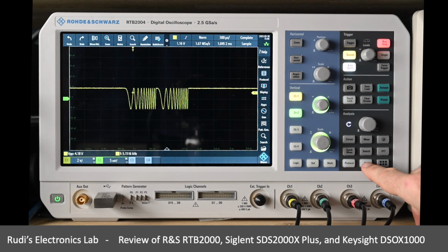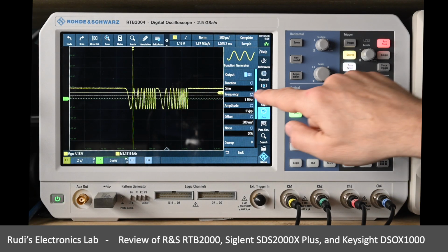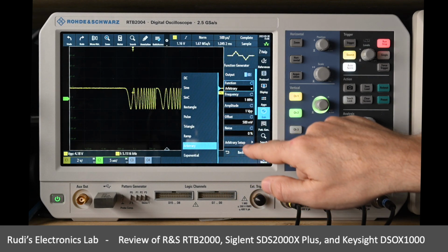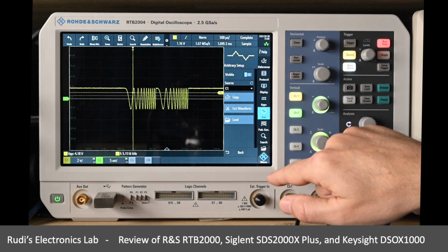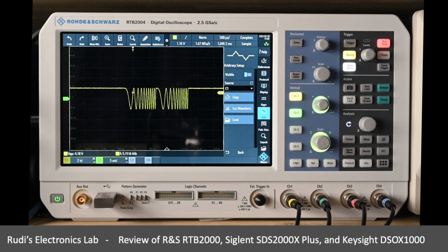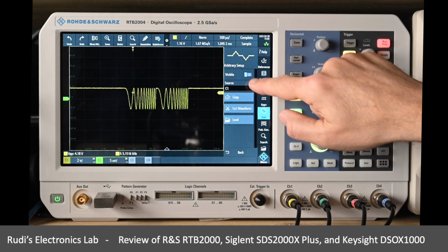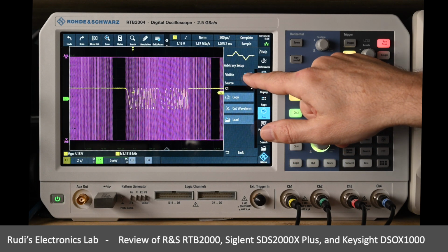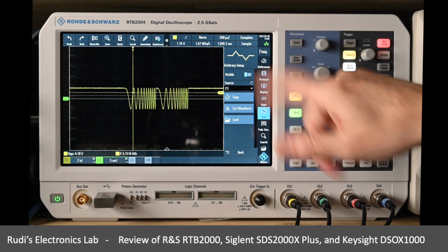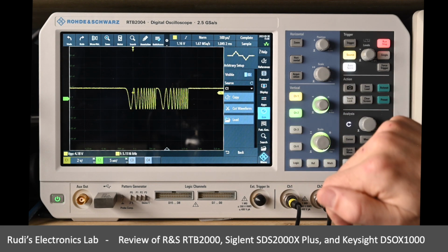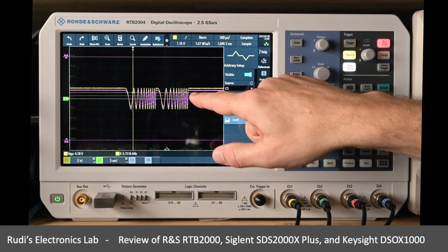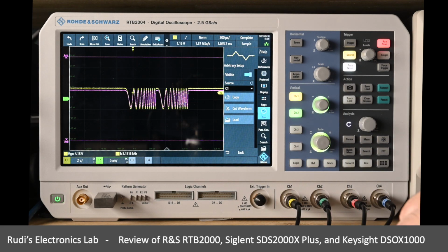Okay, now I'm going to the waveform generator. I'm going to choose arbitrary waveform, and from there I can go to the setup menu. And this is basically where I do the copying. I can make the waveform visible, and what I see here is actually a previous waveform that is still there from an earlier exercise. Now, copy source 1, that's the source I want to copy. I click the copy button and I do see a copy having been made.